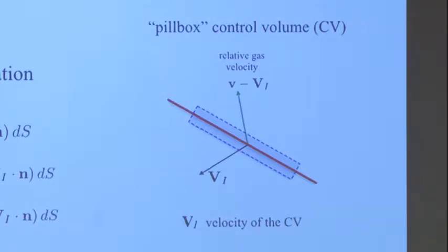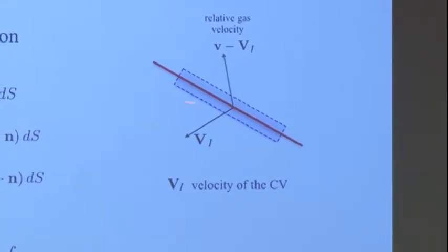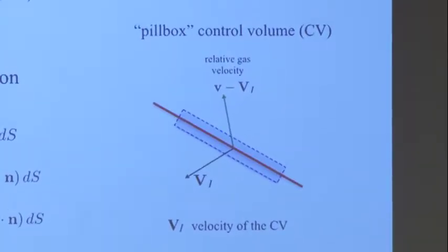Well, two things. One, sometimes the fluid dynamic equations allow you to have jump relations in the volume that you have, provided they satisfy appropriate relations. And we want to derive these relations. But second, this is useful in order sometimes to determine boundary conditions. For example, if you have a fuel droplet of liquid and you want to determine what are the boundary conditions at the surface where it evaporates and burns or doesn't burn, the boundary conditions will be determined by essentially these interfacial conditions.